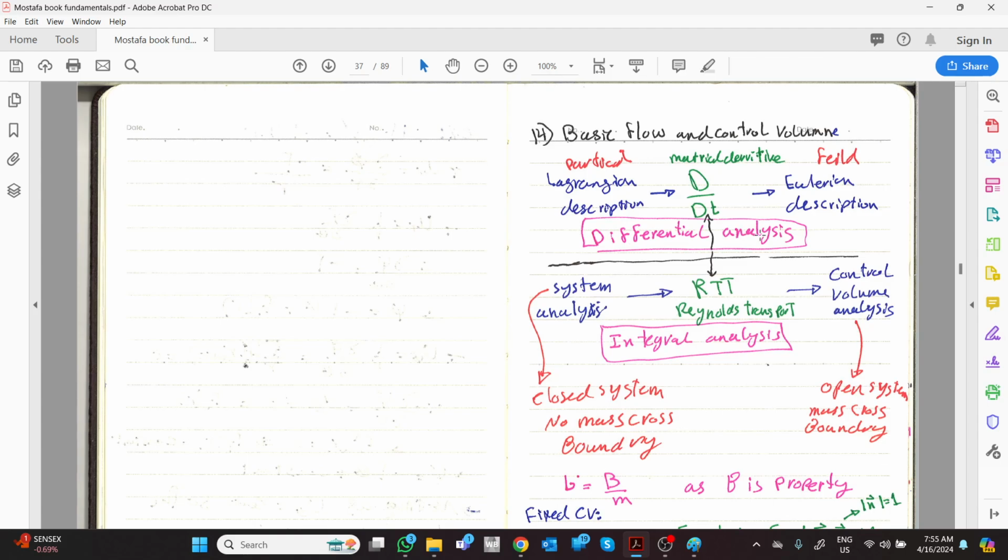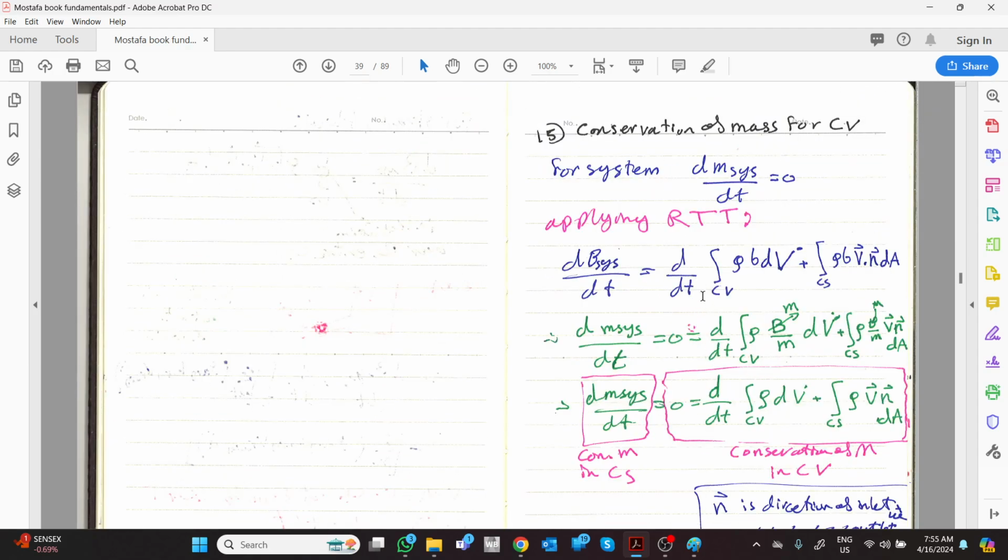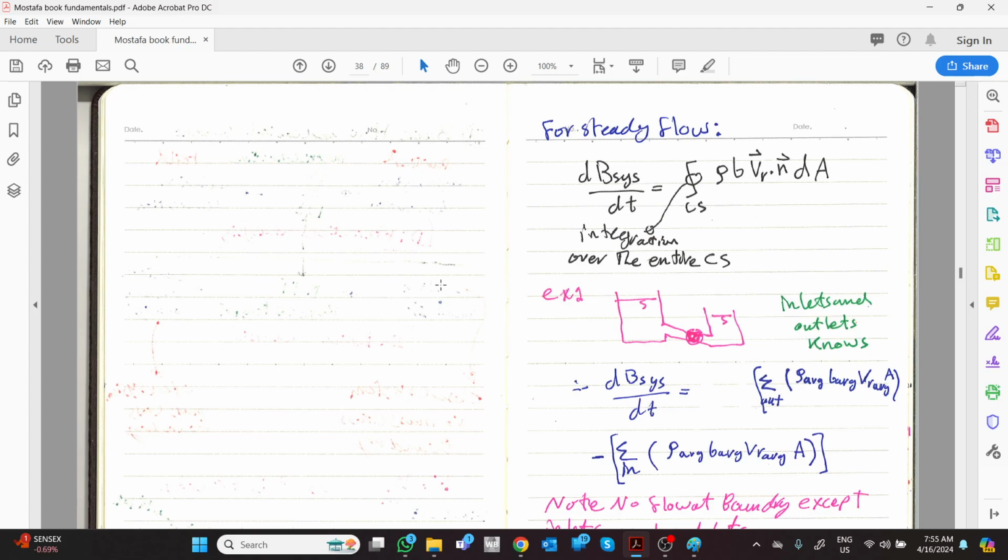But in ideal cases, don't use the derivative method, use the integral method if you know the control system, which means you know some boundaries and it is closed, or it is very simple to apply that theorem, like tanks and pipes, which means it is entirely closed. Remember, in potential flow and Navier-Stokes, we never open a subject like: I have a tank and a pipe and I need to check what the fields are. I can do it, but it is much easier to use a control system.